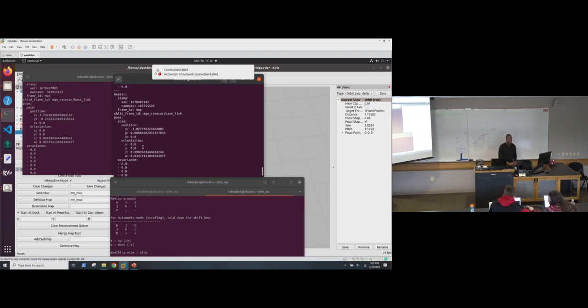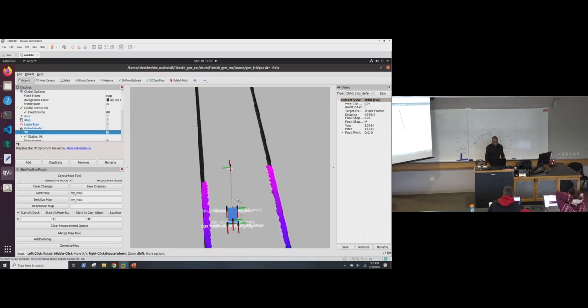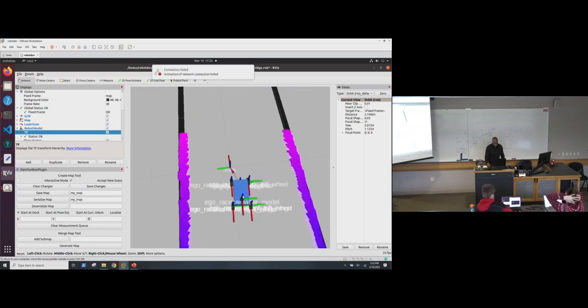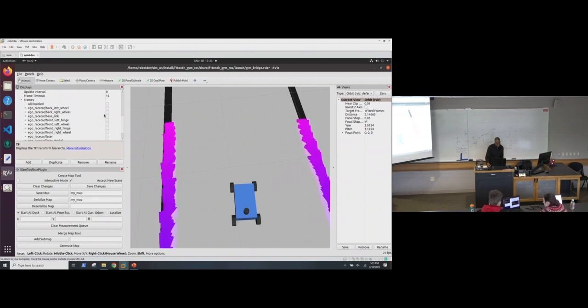Yeah. Thank you. But that's how, in a way, you get the position and orientation of your robot. And remember, that's going to be at the base link. So you have to figure out where that's at. That's going to be the base link of your robot, and that's not taking into account, look at your bases again, it's at the back of the vehicle. So you have to take into account the size of your geometry as well.